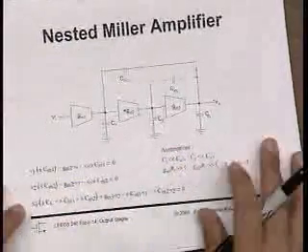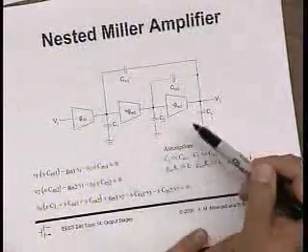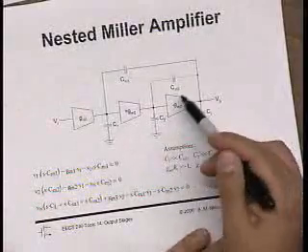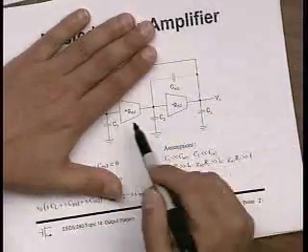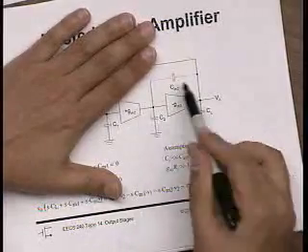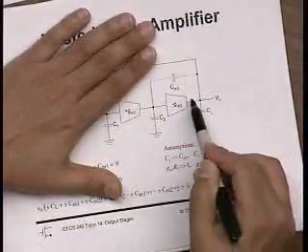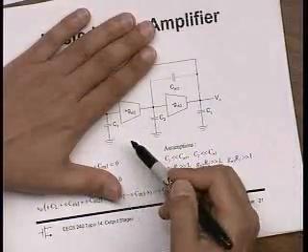So let me just show you what we mean. Here's an amplifier stage. Here's the output stage. Let's say it's a three-stage amplifier. Let's start out with a two-stage amplifier. If this is a two-stage amplifier, this is my second stage. I use Miller feedback around it, and that produces a dominant pole system. So I have a high-frequency pole now and a low-frequency pole.